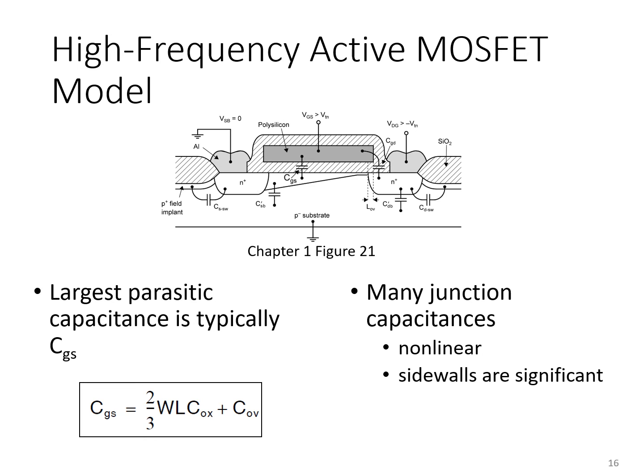You've actually got an inverted channel here, so it's connected somewhat to two terminals. Then you've got this extra term here, COV, which is the so-called overlap capacitance. That is, it captures capacitance that may arise due to the close proximity of the gate and source region here. Similarly, overlap capacitance arises between the gate and drain, although it's not shown explicitly.